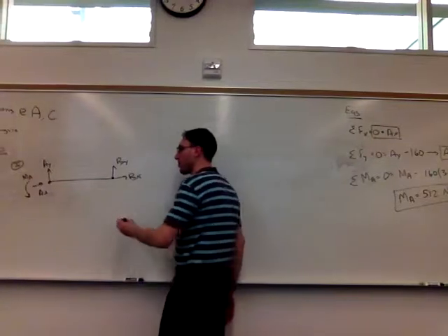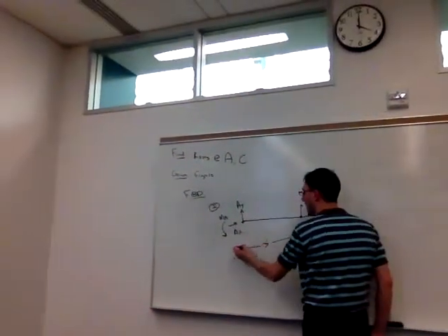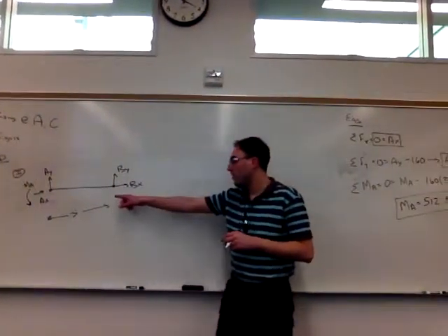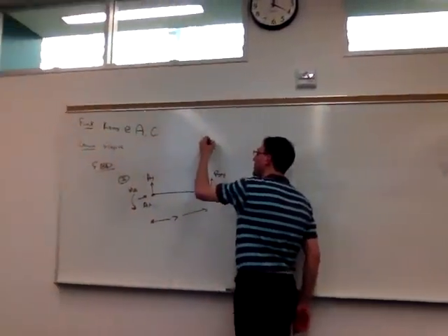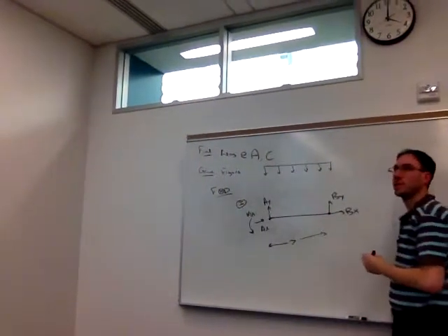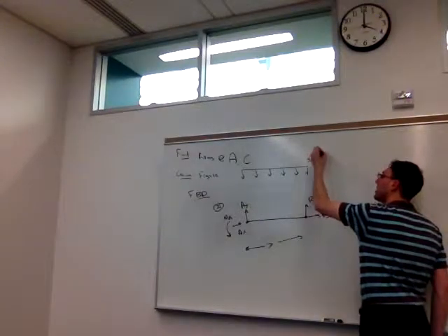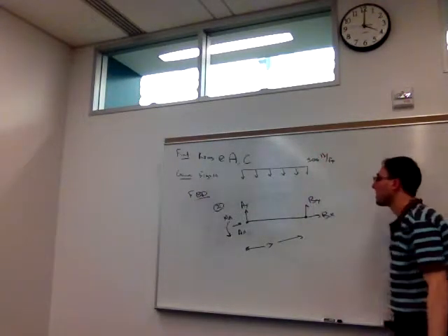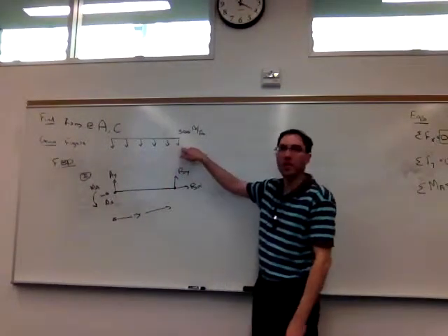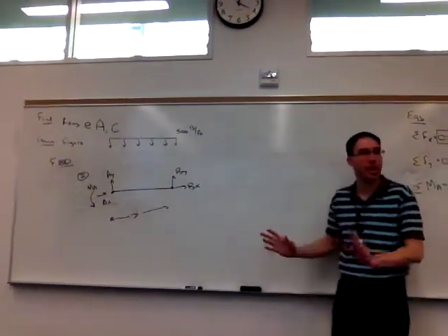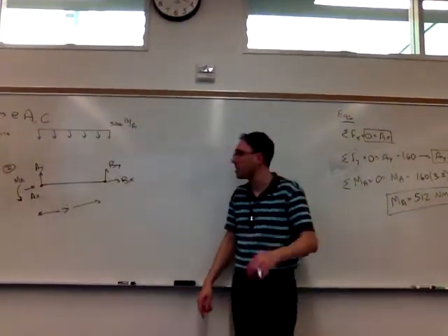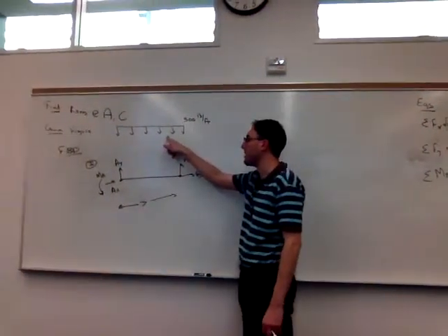We're only considering this 3-foot section that goes from A to B, where it's then pinned together to the other beam. This section only sees, I'll draw this temporarily up here, this much of the distributed load on it with a constant value of 500 pounds per foot. This section of beam doesn't know anything about the amount of the distributed load that goes from B to C directly. It doesn't see that weight directly. It will be influenced through the BY, BX values,